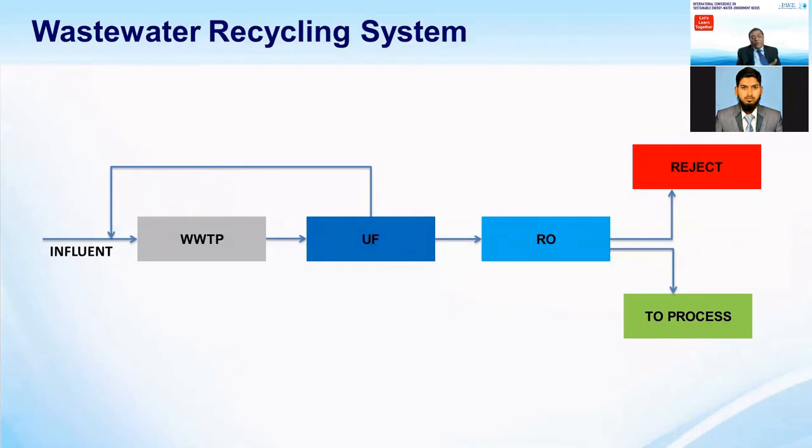What is the source of water? What contaminants are there? Only a well-designed pre-treatment can lead to the reliability of the RO system. Operation and maintenance will be reduced, and you can enjoy your life if you have a good pre-treatment. That can only be designed if you provide the detailed analysis to your vendor, the EPC contractor, or the membrane manufacturer.